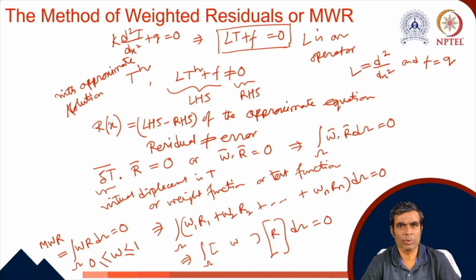In Rayleigh-Ritz method, we needed the self-adjoint operator. If it is not a self-adjoint problem, we cannot use Rayleigh-Ritz method. But for the method of weighted residuals, there is no such restriction. Any kind of differential equation, be it linear, be it non-linear, be it in solid mechanics, be it in fluid mechanics, be it with symmetric operator or with asymmetric operator, we can use the method of weighted residuals. Okay, so for the method of weighted residuals, I already told that there are 4 fundamental parts.